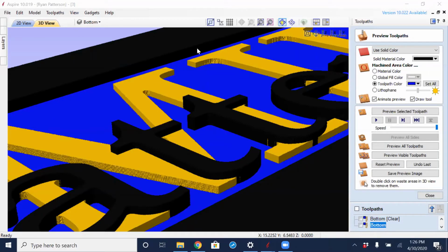So just to confirm our different levels or heights, on the 3D preview side, you can hover your mouse over top of the areas, and in the bottom right section down here, it gives you the X, Y, and the Z value for this. So knowing that this is the top, which is at 0, then we have the section here, which is our main family, and we can see that's a -0.1, and hovering over the blue, we're down to a -0.2.